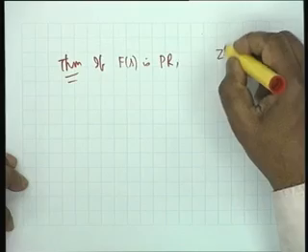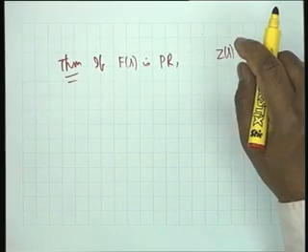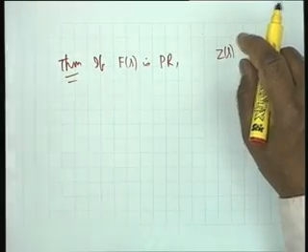Oh, we don't have to prove it, because Z of S after all is made up of SL, 1 by SC and R. Each of them is real for S real, and it will only be series parallel and multiple series parallel combinations. So all of these quantities would be real for S real. That is trivial, but this is not trivial. That real part of Z of S is non-negative is not a trivial proof.